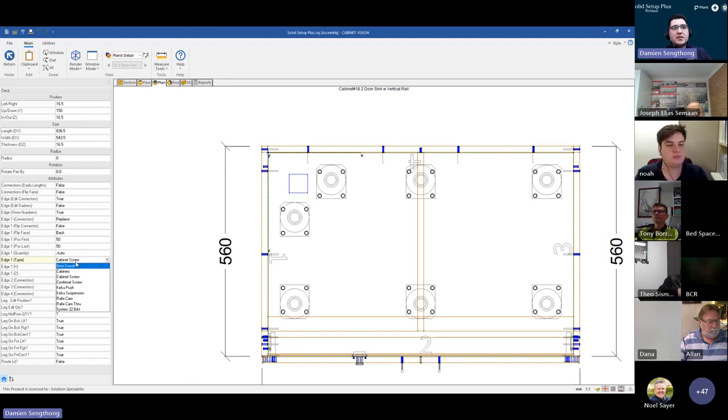If your business happens to do dowel construction, we do have an option for 8mm dowels, cabinet fittings, Confirmat screws, and Kiku clips. In this situation, if you have a fixed panel and you don't want any fixings from the front, a Kiku clip is efficient.